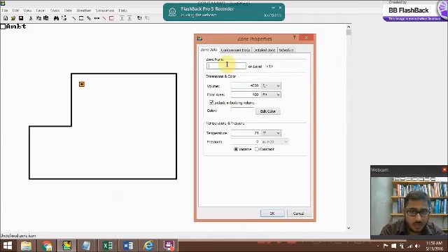You have to give a zone name. It would not accept the zone properties without a name. Spaces are not allowed in any names inside Contam. So wherever you are specifying names, you have to make sure you don't have any spaces.